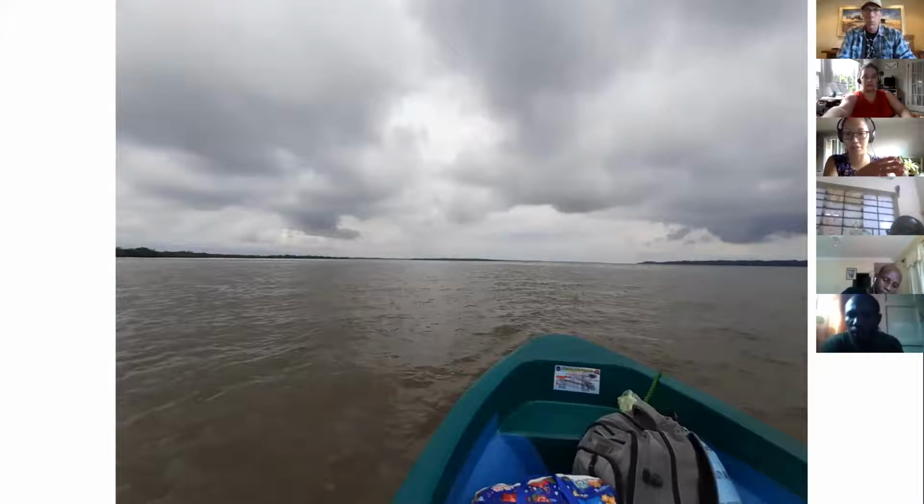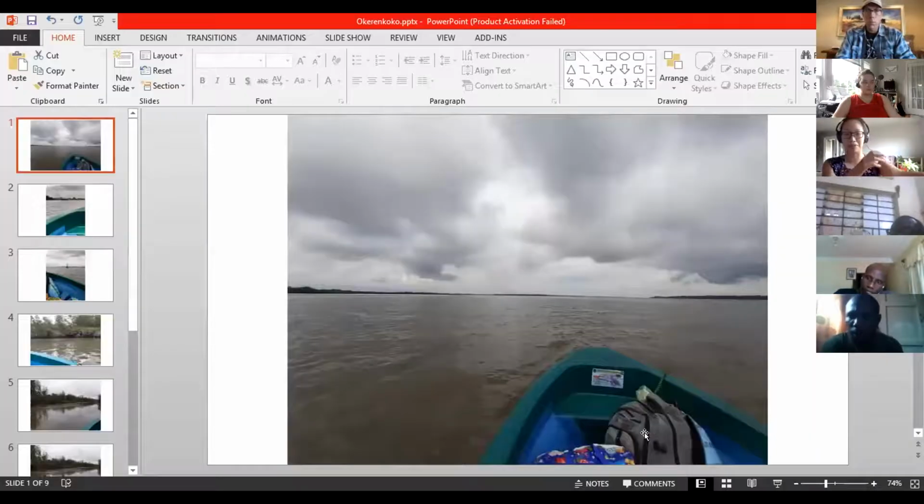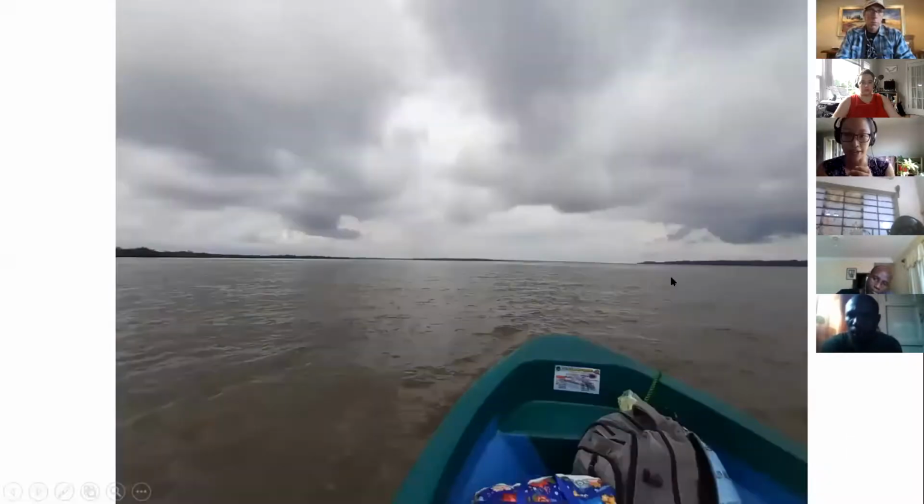So, how the concentration is changing as you move along the river, which is also going to be confounded by the river moving. But if you are moving at the same rate as the water, traveling with that water parcel, it will tell you whether it's changing from other inputs along the river. Or, staying in one spot, you see how the concentration changes as the river moves along throughout the day. That will tell you your daily variability, and then you can do that once a season or so, and that can tell you how that daily variation changes seasonally.